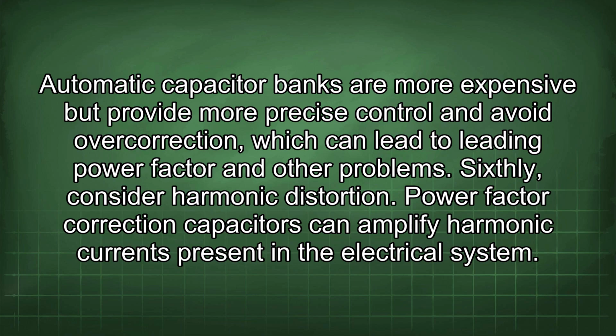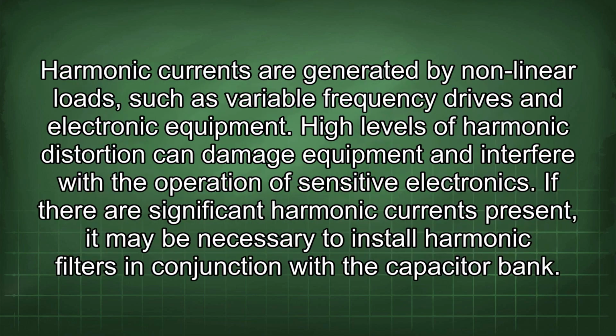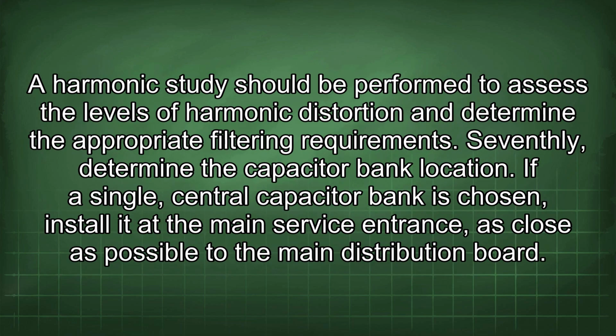Power factor correction capacitors can amplify harmonic currents present in the electrical system. Harmonic currents are generated by nonlinear loads, such as variable frequency drives and electronic equipment. High levels of harmonic distortion can damage equipment and interfere with the operation of sensitive electronics. If there are significant harmonic currents present, it may be necessary to install harmonic filters in conjunction with the capacitor bank. A harmonic study should be performed to assess the levels of harmonic distortion and determine the appropriate filtering requirements.